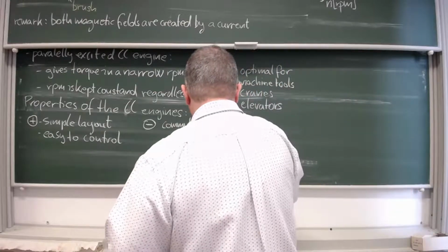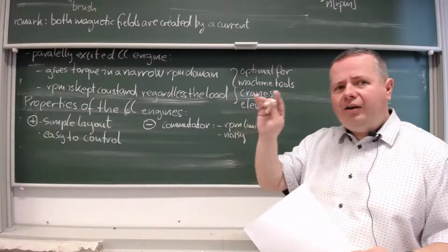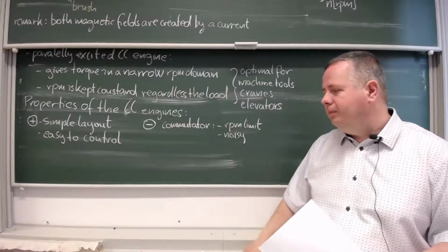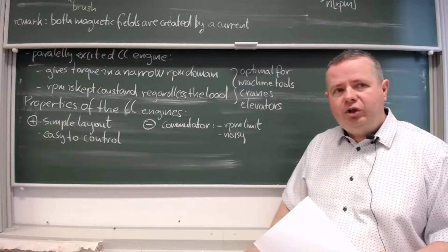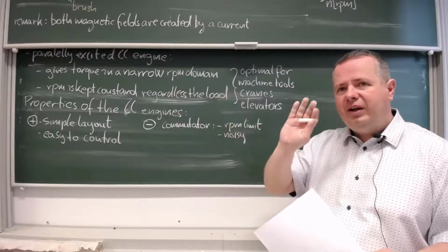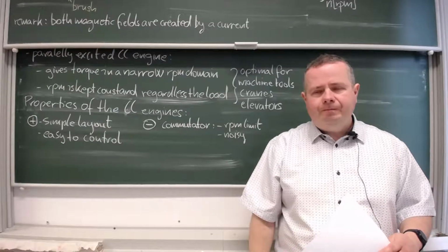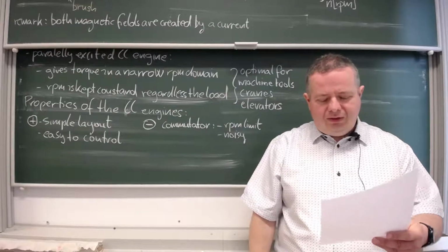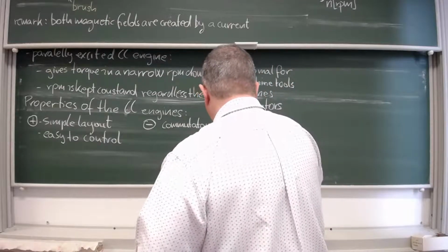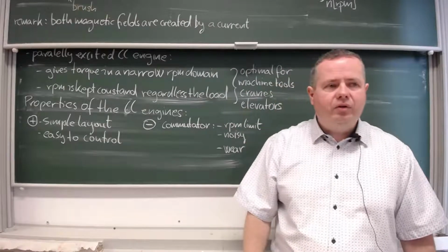It's also noisy because you get a high frequency noise because the wire and sheets are entering and leaving the brush surface. It's like a continuous abrasion noise. And what else? The wear. Wear of what? The wear of every part composed in the commutator.